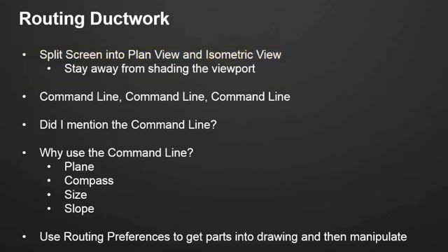So I like to keep my screen split, but I certainly don't like to shade my viewports. I see a lot of people that shade them either in a conceptual view or a realistic view, and if you have a really powerful computer, then by all means go ahead and do it. But the shading really just takes away from your computer processing power and slows things down.